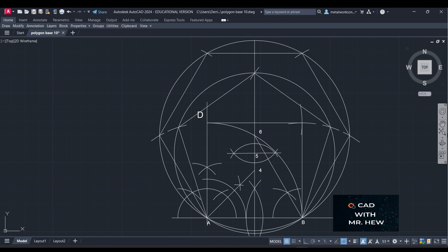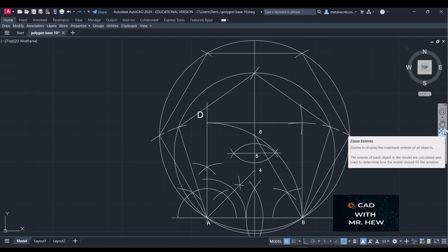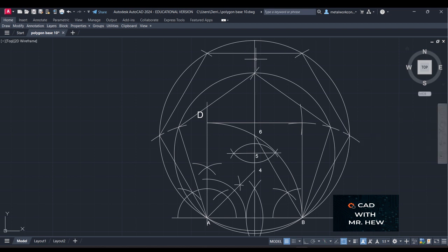Good. All right. Now the next thing we're gonna draw is where the center for 7 would be along this bisector that we drew earlier on. All right. So we're gonna take our compass. We're gonna put it at 5, open it to 6. Then we're gonna move the compass from 5 with the same radius. Put it at 6 and mark an arc, as I said previously, to give you 7, 8, 9, and 10.